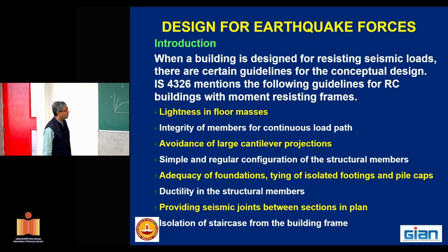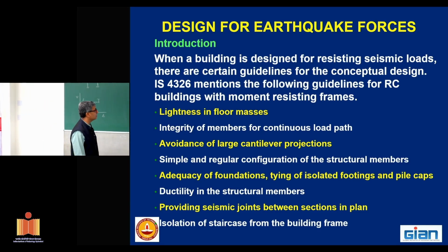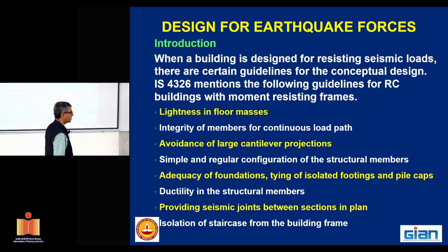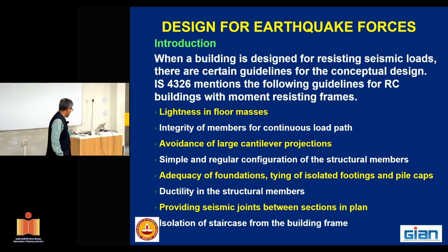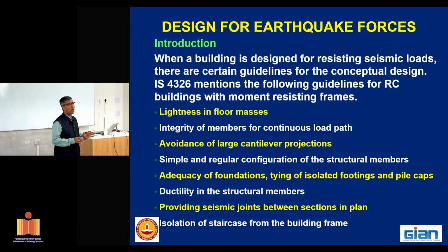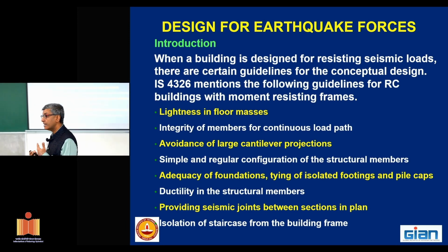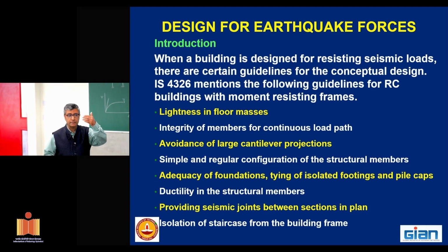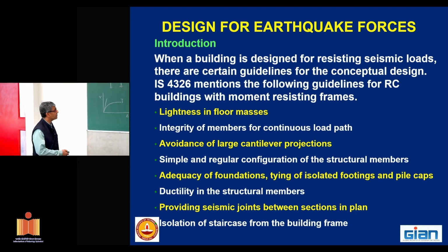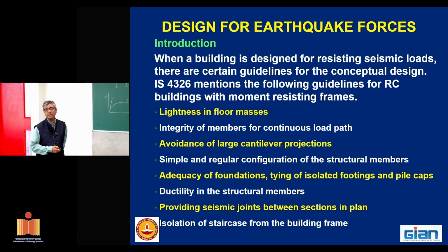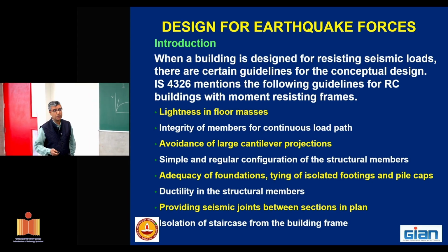Now, when we are going for the design for earthquake force, it is not just that you calculate some force and do the analysis. You have to start with a proper configuration so that your forces are less. Hence there are some guidelines in the code that first of all we should not have unnecessary heavy masses. People are having swimming pools at the top, and you saw in Thailand what has happened. Integrity of the members, it is not just designing the members, the connections are the most important.